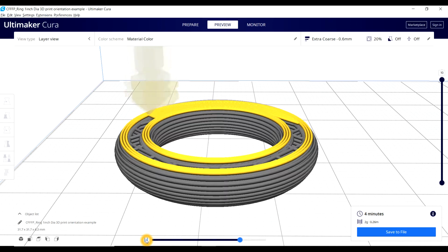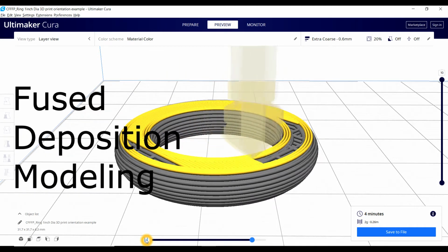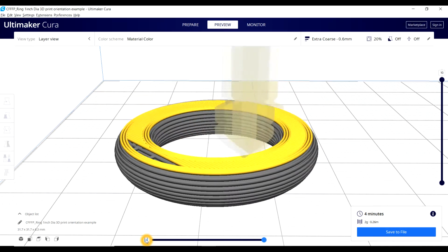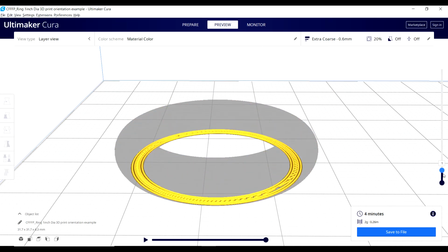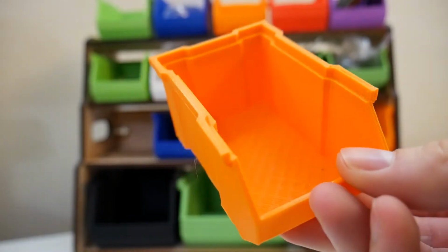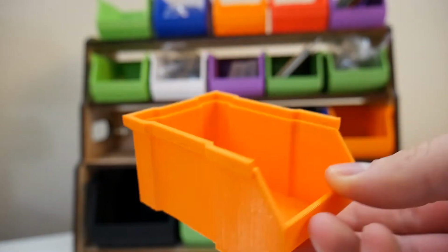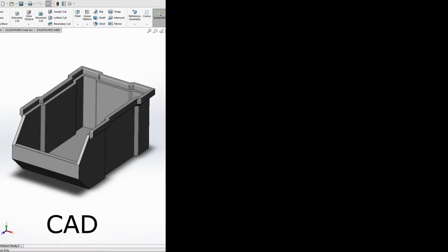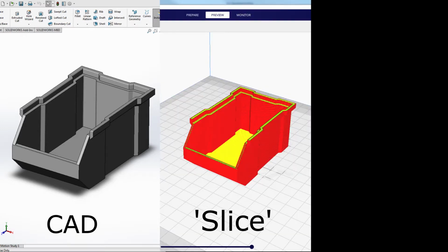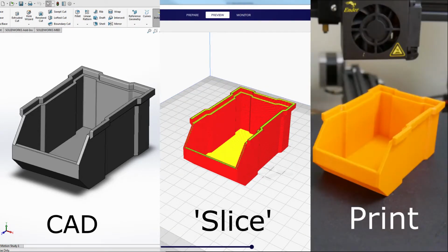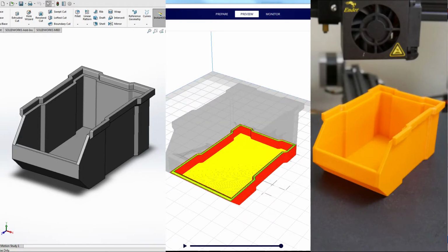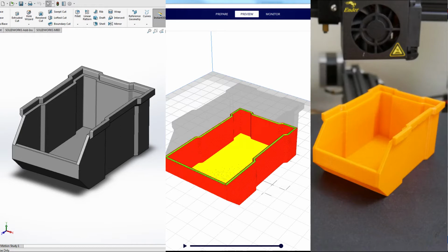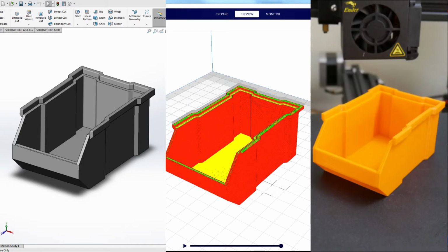The most prevalent type of 3D printing is fused deposition modeling. FDM 3D printing is the process of extruding molten plastic to build a 3D model layer by layer. From idea to physical part, this process is comprised of three fundamental steps: creating a 3D model, slicing it, and finally printing it. The slicer software converts a 3D model into layers and reproduces the model as G-code, which are X, Y, and Z coordinate instructions telling a machine to move the extruder, building the model layer by layer.